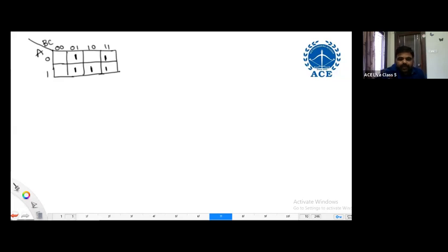Okay, back up. Very simple. Let us see that. Very good, some of you are doing very well. Let me help them. Let us find the number of possible groupings to say the number of prime implicants. This is one grouping, second grouping, third grouping, and fourth grouping. The number of possible groupings is 4. The number of prime implicants is also 4, since the number of possible groupings which cannot be expanded is 4. In these, how many groupings are having special cubes?